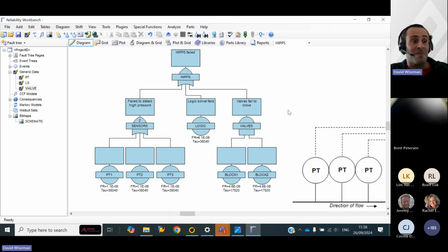Maybe a power surge might cause several electronic components to fail simultaneously. Components that normally would fail independently of each other could all go down at the same time because of one problem. Now, there are different ways to model that in a fault tree, but again, keeping on theme with IEC 61508 and its associated standards, I'm going to take an analytical approach and use a beta factor model.